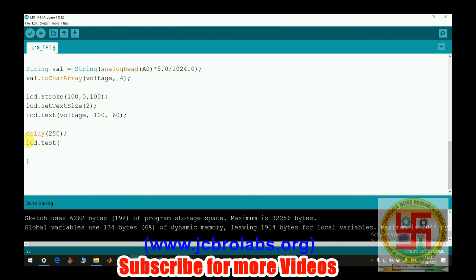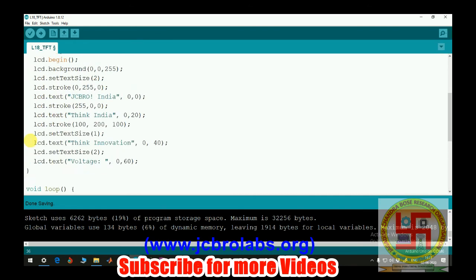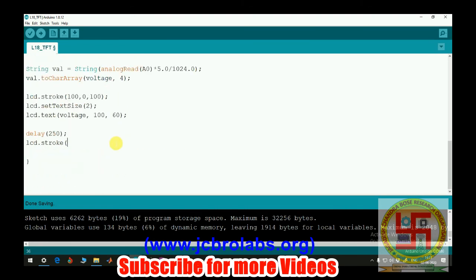So first we change the stroke to that of the background. The background is 0,0,255, so 0,0,255, and then LCD dot text, again voltage at the same location 100,60, and it will keep repeating at an interval of 250 milliseconds.